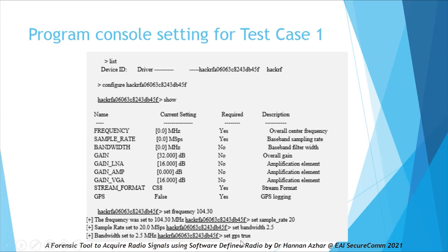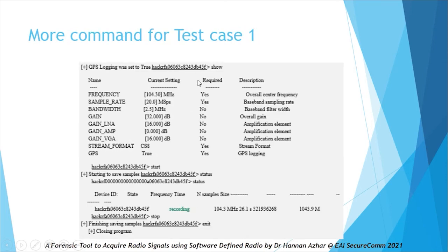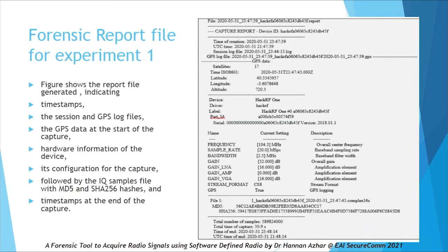Now the next experiment I want to report is about the intruder attack on the garage door. Basically this is 10 bits of data in amplitude modulated data, ASK, on-off data. And fixed code means that this garage door has got a fixed code, and you send the data, and if you know this data, then you can actually open the door. So basically you brute force the 10 bits, the 10 different combinations.